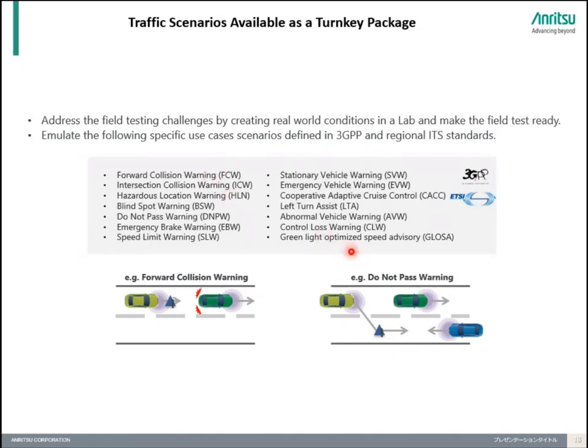And again, for a developer, you are not limited to these 14 scenarios. You can always create your custom scenarios and test your CV2X module further. But these are the standard test cases that are defined by ETSI and the regional ITS specs. So the same thing is also readily available in our solution. You can see popular scenarios like forward collision warning, blind spot warnings, emergency brakes, and left turn assist, all available readily.